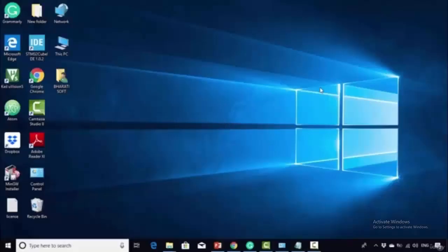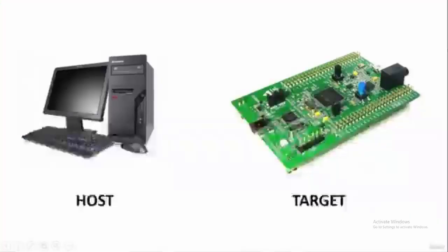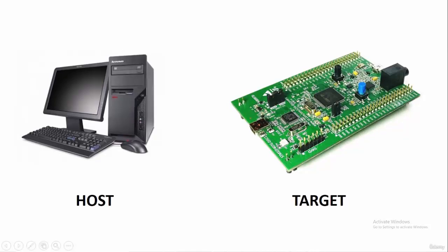So in this lecture, let me show you how to create a project using STM32CubeIDE. In this course, sometimes we will be creating projects for our host. That means the project which is going to run on our host machine. So in my case, the host machine is an x86 64-bit machine. And sometimes we are going to create projects for our target. And the target in our case is an STM32 microcontroller based discovery board.